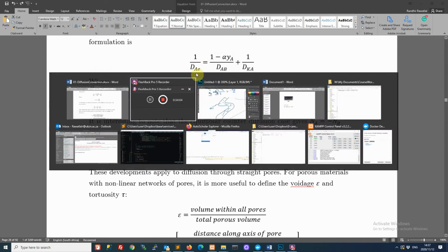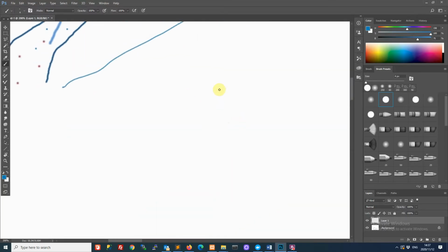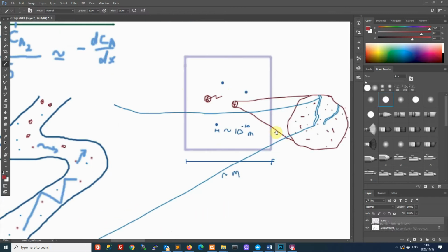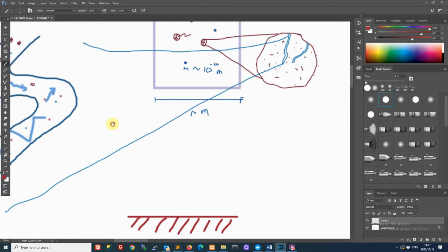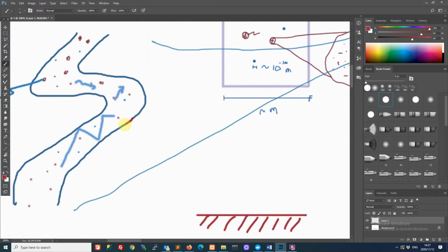And then, as we promised, let's talk about when we might have equimolar counter diffusion. So let's imagine that we have a reaction surface here. So this is talking about, for example, our particles. Excuse me. So let's say we are talking about in the pores here. We have a catalyst center, and so our component A arrives on the center. It reacts, and then component B forms and moves off. So our reaction is basically this one. Our reaction is A goes to B.